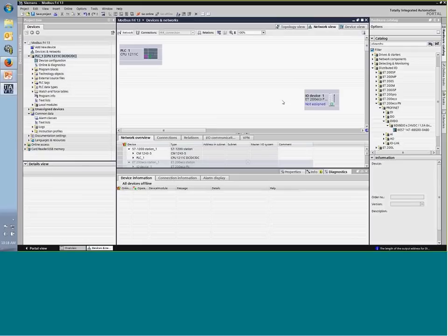Going back to the point of how easy and interactive the TIA Portal software is, networking typically gets really complicated, but not with TIA Portal. You see the green box right here, which represents Profinet, and there's a green box, which is our Ethernet Profinet connector on our base CPU. We select the green box and drag and drop a line and connect it to our remote distributed IO. You see we just created an Ethernet connection between our PLC and the remote IO.